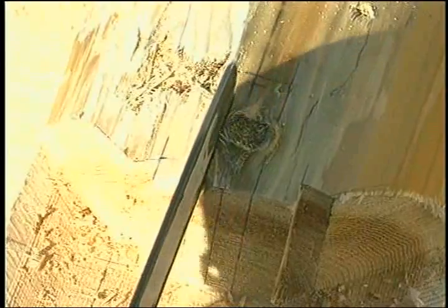Try to keep the keyway cut straight and an accurate fit to the key material you plan to use. If the cut is too tight, it will tend to split the log end, and if it is too loose, it will not do the job as well. It may pay to do a little practice before you do this first keyway cut.